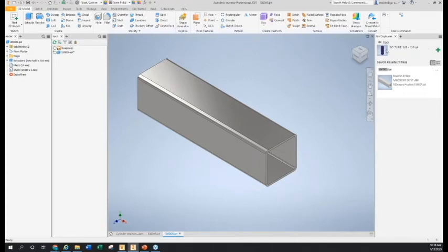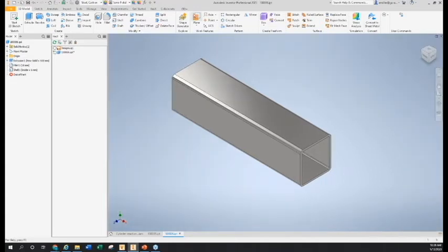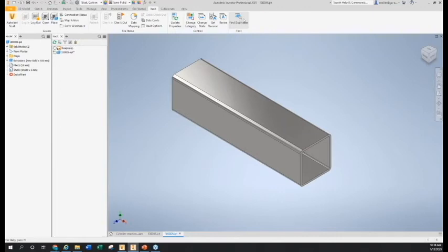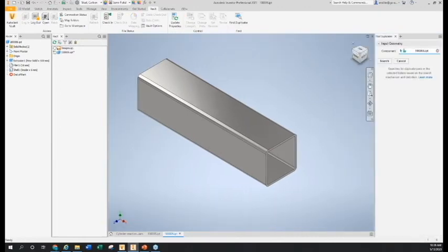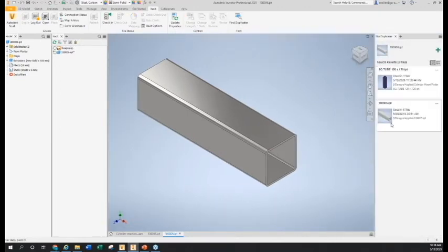But now, let's go back. I close that out here, let me go back to Vault and do a find duplicates and do a search on this one. This one actually found two out there: the one square tube that I had in that assembly is out there, plus the other one, 1005. You can see this one is a new part. It isn't in Vault yet. You can see the plus sign there, but this one was created completely differently.